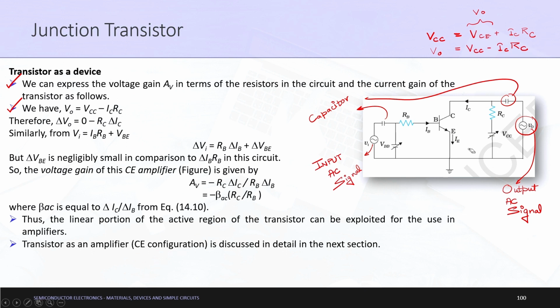So, in this complete Kirchhoff's rule formulation, which we also used when understanding transistor as a switch, let me make you understand why a capacitor is installed here. If you have revised the concepts of electrical charges and capacitors, from a previous chapter in class 12th, the main use of this capacitor is that the direct current should not pass through it. The capacitor does not allow the passage of direct current. It will only allow alternating current. Hence, the current will be passed through here, and the complete summation will be passed through here. Therefore, there will be a change in IB. With the increase or decrease in IB, there will be a change in IC, and due to this change in IC, there will be an effect on this VCC. That is how this complete formulation occurs.